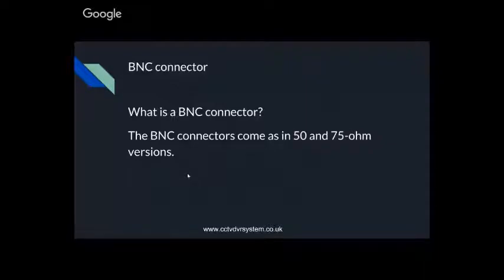So BNC connector comes in 2 different types, 50 ohm and 75 ohms. Depends on your cable impedance, you have to select the right one. For CCTV application, we normally go with 75 ohm BNC connectors.